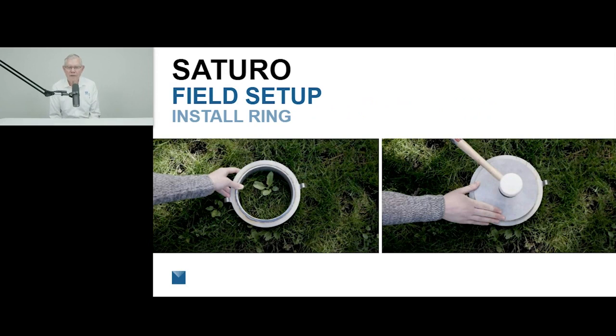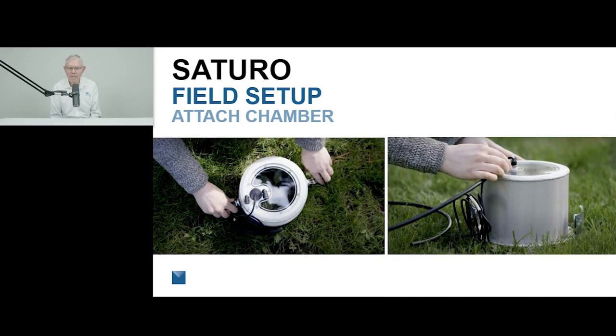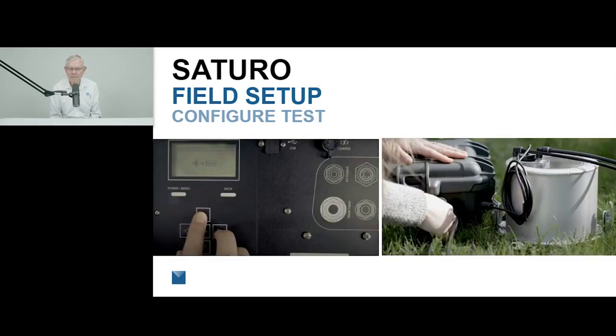I'd like to share a few slides showing how a measurement is taken. We start by selecting a location for the measurement and driving the infiltration ring into the soil with a hammer, as I'm showing here. The chamber's then clamped onto the top of the ring and sealed, and the electrical and hydraulic connections are made to the control unit. The measurements are started using the control unit keyboard. Then we just leave it to make the measurements.